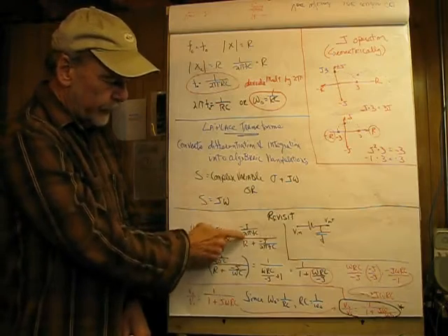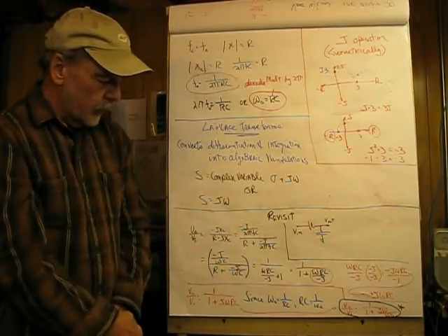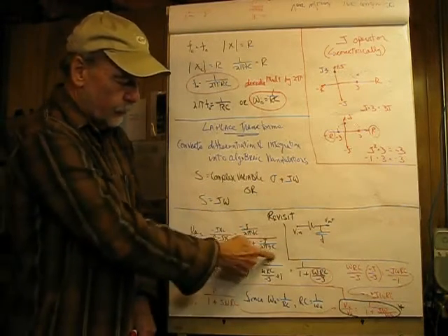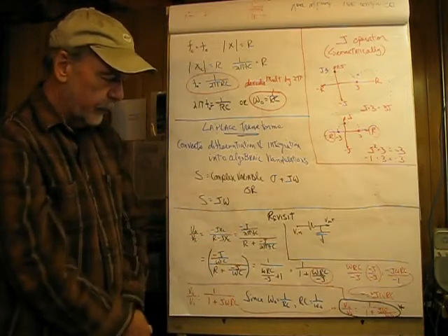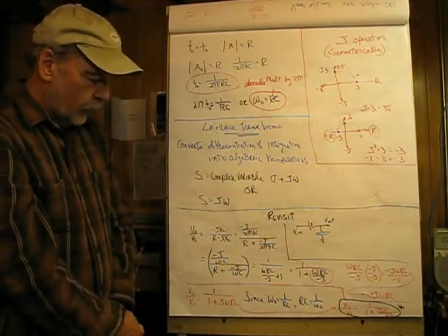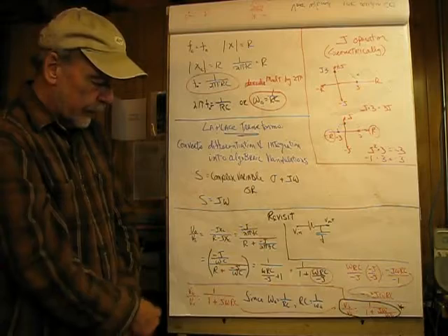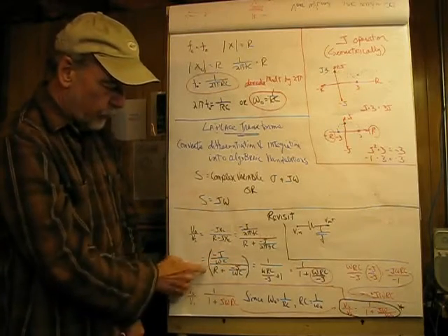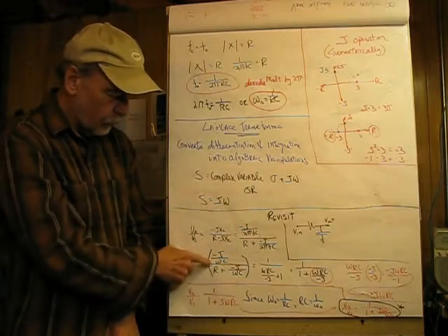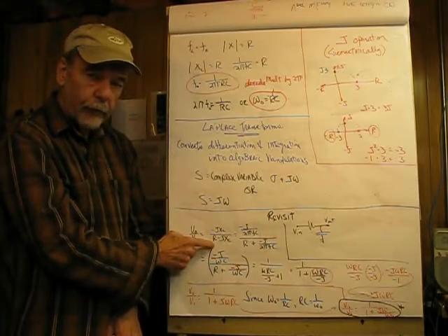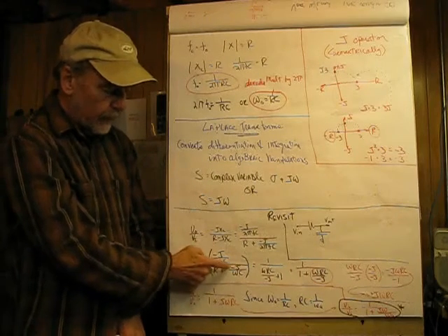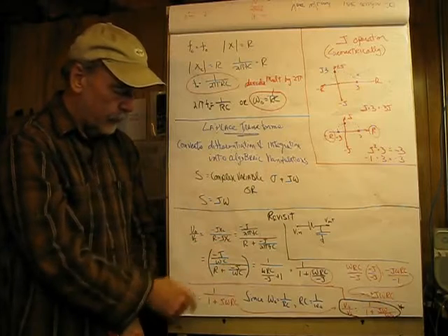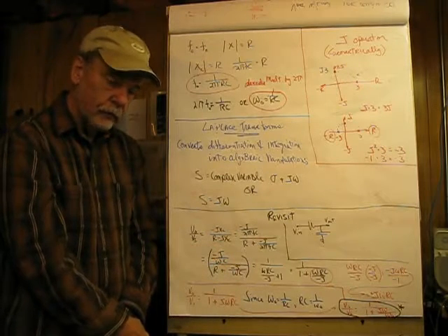And here I've expanded that into the actual capacitive reactance equations for the numerator and denominator. And then what I'm going to do is clean this up a little bit. I'm going to multiply this equation by its inverse, omega C over negative j. And I have to do both the denominator and the numerator so I don't change the value.